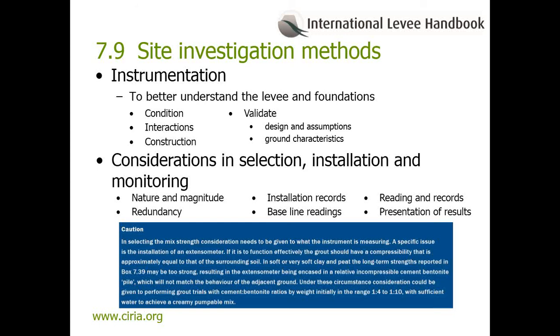provide construction control in terms of settlement and the avoidance of the onset of slope failure or instability, and validation of design assumptions and ground characteristics through pre-construction trials. The section primarily considers instrumentation which is capable of monitoring displacements and pore water pressures, although total stress, seepage, discharge, soil and groundwater temperature may also be monitored.